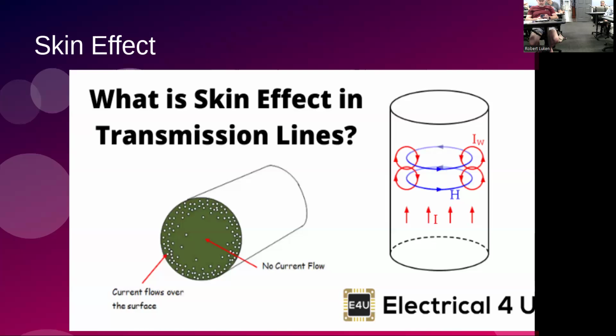So when you get to very high frequency stuff, it doesn't have to be a solid conductor, because there's no current in the middle. It can be a tube. In fact, you'll notice most antenna elements, as they get any size at all, become aluminum tubes because the current is going to be on the outside. You have the same kind of effect on very high voltage power lines because of the electric potential.